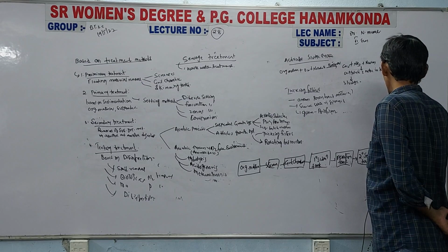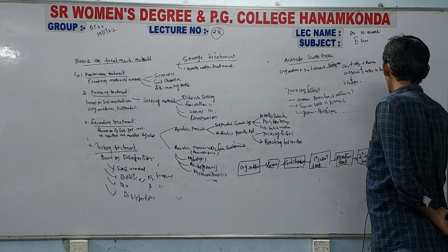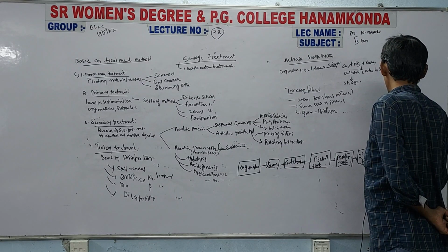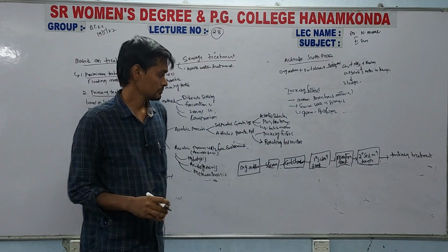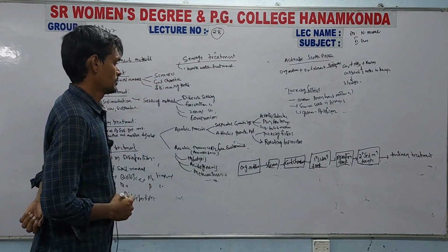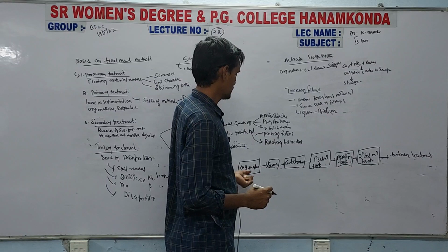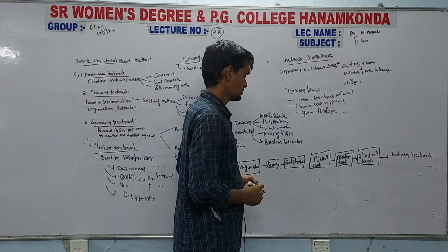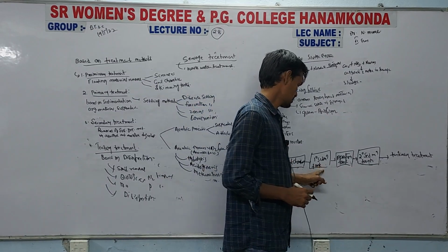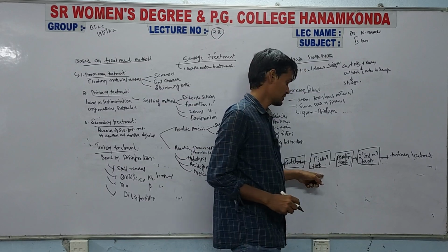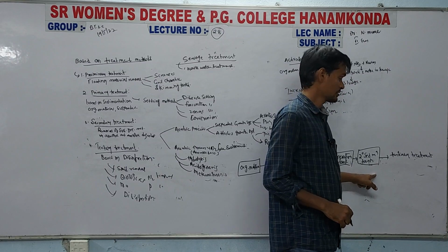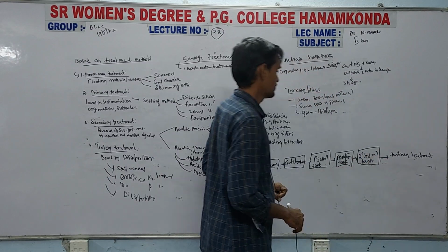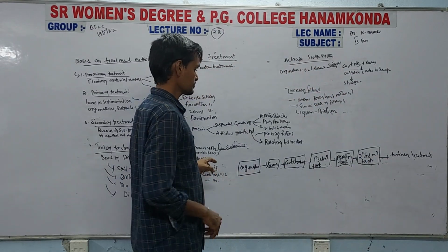and finally tertiary treatment. So, the organic matter is passed through screeners and grit chambers, and from grit chambers it passes through the primary sedimentation tank, aeration tank and secondary sedimentation tank, and then it is tertiary treatment.